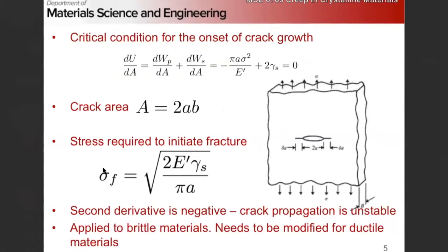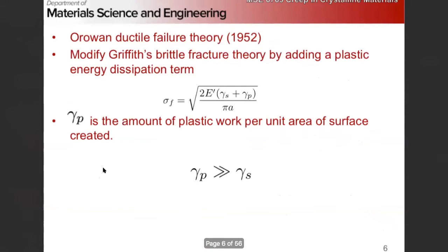In crack growth, in the brittle material, there's no plasticity. So it just depends on balancing the potential energy of your system against the surface of the crack. For ductile material, you allow dissipation of energy through plasticity. So not all of the stress you put into the material is going into stored strain energy.